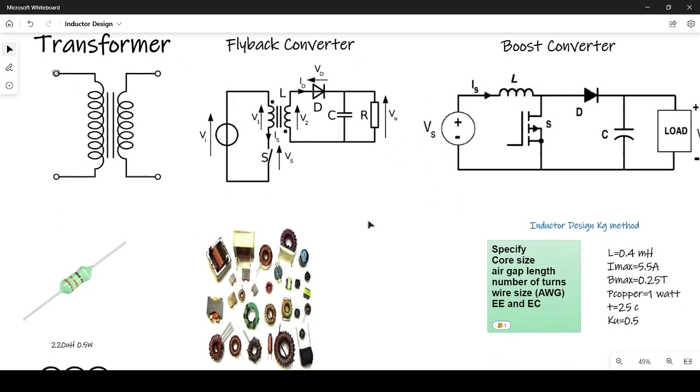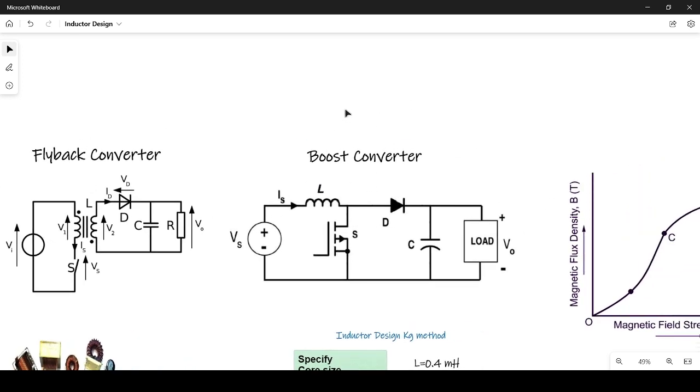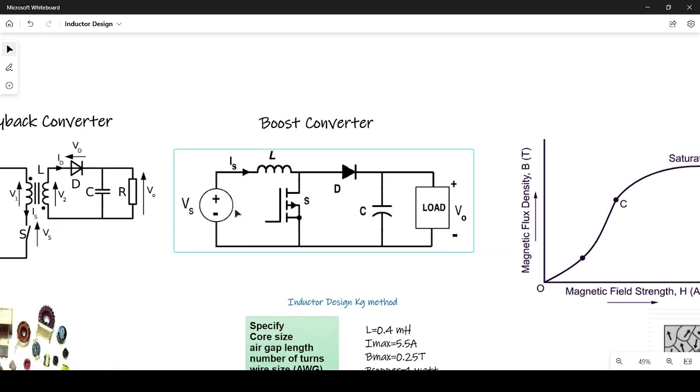We are not designing transformers specifically, we are designing an inductor. So we are more interested in boost converters. In a boost converter, we have a MOSFET. This MOSFET is to open and close this circuit repeatedly to provide some changing voltage to this coil to amplify this voltage to this circuitry. And this is a rectifying diode and capacitor like a filter. We are not interested in details about this boost converter. We just want to use this example to understand more what is happening here.